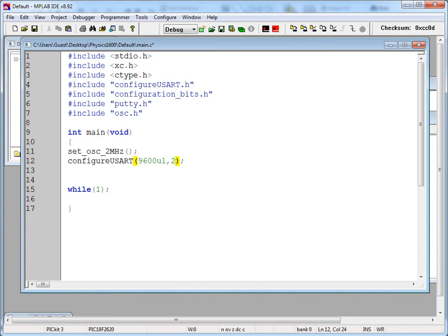You might ask, so what? Well, sometimes you want your chip to operate really fast, and at other times you want it to operate very slowly, because when it's operating slowly, it doesn't consume as much energy. So if you were to put this out in the wild, you don't want to come back and change the batteries all the time. So you would operate it as slowly as you need it to. And so this is a nice flexibility of this chip.